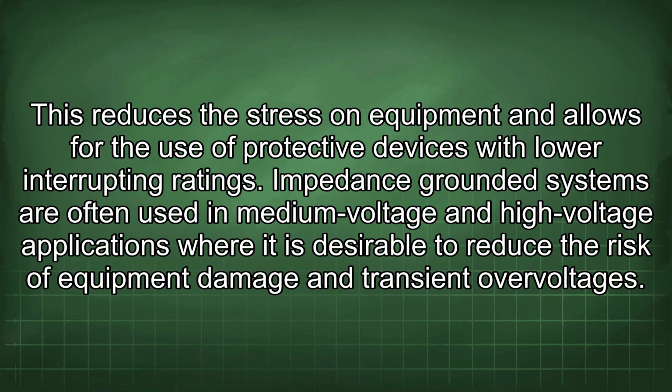This reduces the stress on equipment and allows for the use of protective devices with lower interrupting ratings. Impedance grounded systems are often used in medium voltage and high voltage applications where it is desirable to reduce the risk of equipment damage and transient overvoltages.